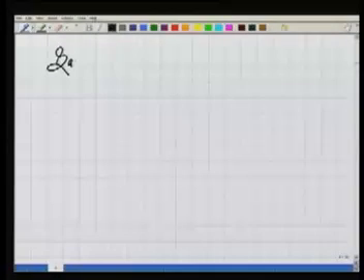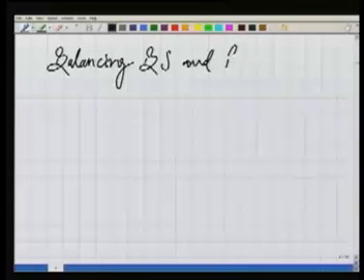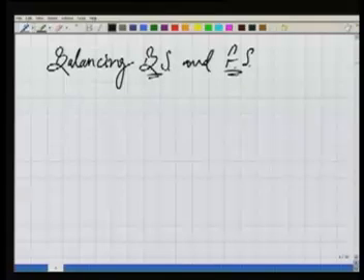Similarly, we will try to do something here. In case of theodolite, we could eliminate the errors by principle of reversal. Something like that we will try to do here also. Well, what can we do? What we do, we say as balancing backsight and foresight. Now let me also explain this backsight and foresight, what these are.